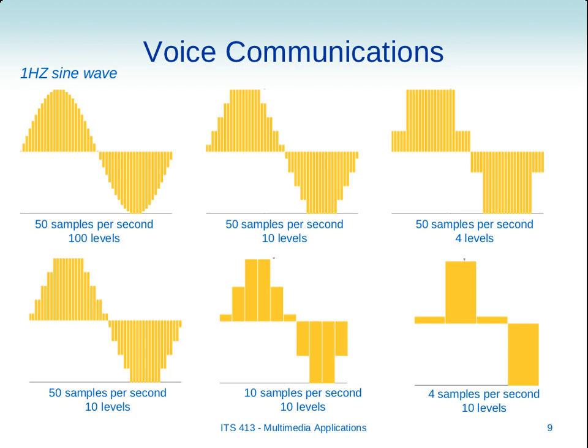So in summary, in terms of quality at the receiver, when we want to reproduce some analog signal that has been sent in a digital form, we get better quality if we have a higher number of levels or a larger sample size, and a larger sampling rate, more samples. That is, increase the number of levels and increase the number of samples per second.